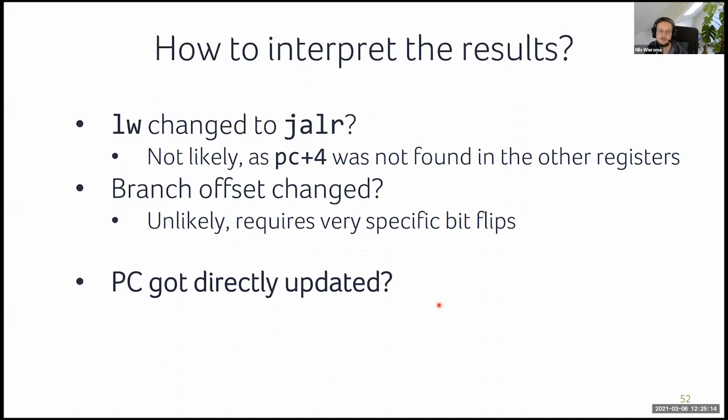And then another possible explanation is that even though we cannot directly load values into the program counter using the available instructions, if you think about the hardware, in the end, the CPU will have one big multiplexer to select which register to use for a value that's somewhere else in the CPU. And even though it's not exposed, this multiplexer will also be able to reach the program counter register because it needs to update the program counter.